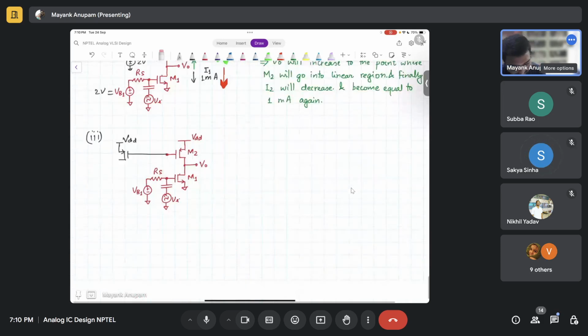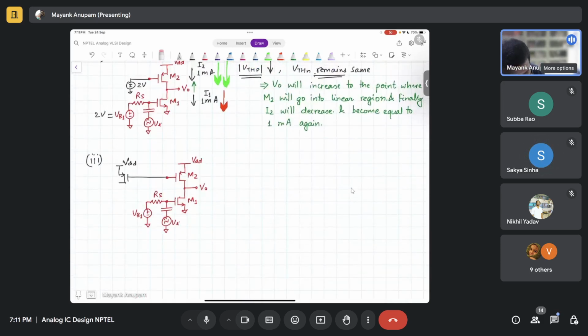Good. So, what I was trying to explain here is, in this condition, the current mirror. Someone said current mirror is a good way to pass, so that is what I'm saying. If you use a current mirror here and you use it this way, you need a bottom current source, right? And this guy has to be connected in this manner. So this is a current mirror. This is M3. So what is the current mirror here? This configuration is the current mirror, right?